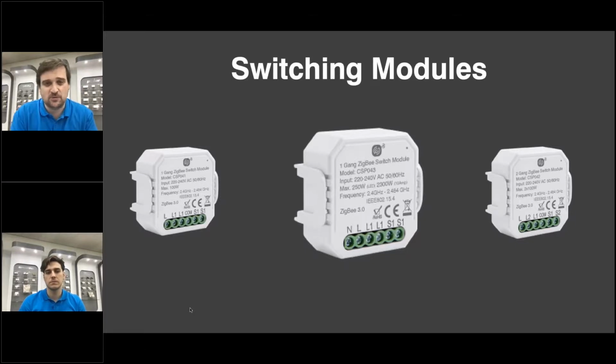This is a very typical switching module. So this will allow you to switch things on and off. It doesn't just have to be a light, it could be an indicator, it could be a horn, it could be a pump, it could be whatever you want it to be. There are limits with these though, typically 10 to 16 amps you can switch these, but there are ways of including them into a traditional system so you can switch larger loads, isn't there?